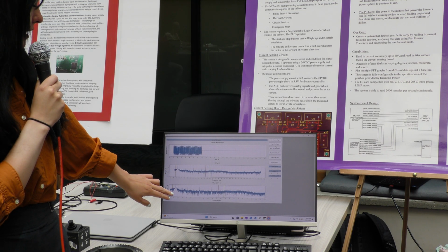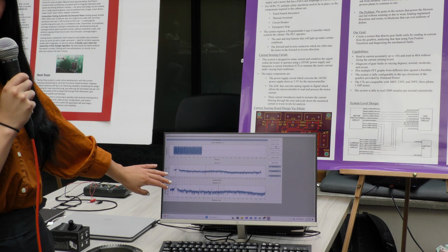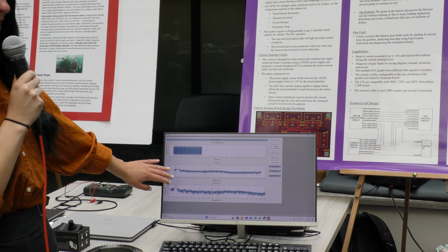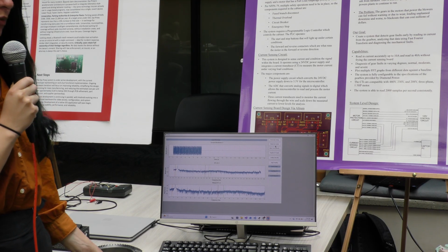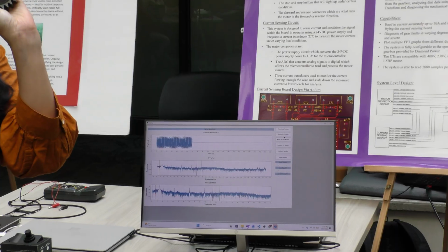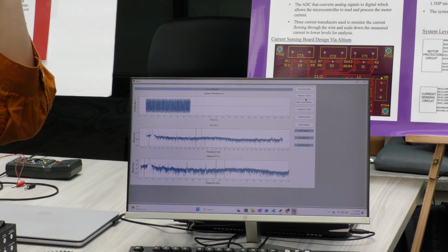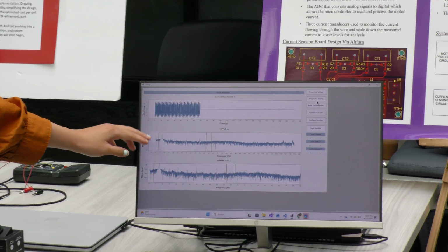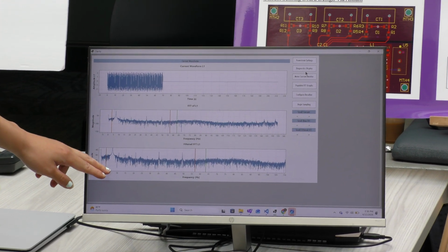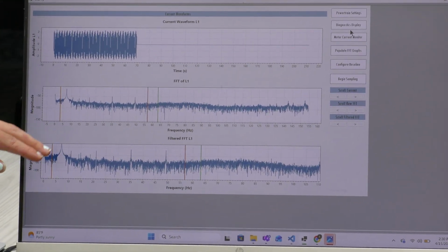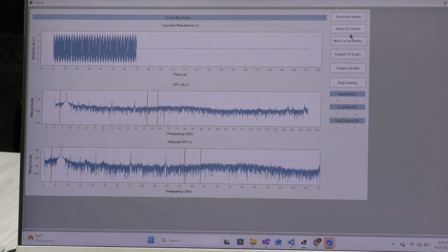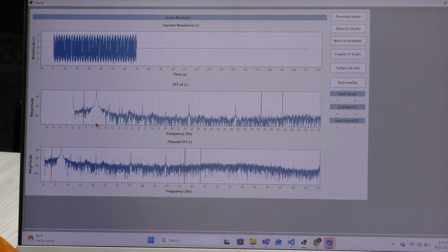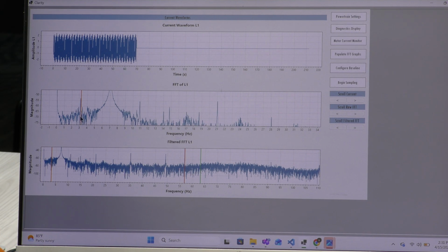And right along here, you can see this is some of the data that we collected. It was a major gear fault that we caused by manually shaving down these gears and switching them out. So we knew exactly what faults would occur. But you can see for this particular bit of data, which was a motor spur gear, that spike, that peak, occurred right where we predicted it to be. Like, seriously, right on the dot. It's kind of hard to see at that distance, but there's a spike right here where that orange line is.